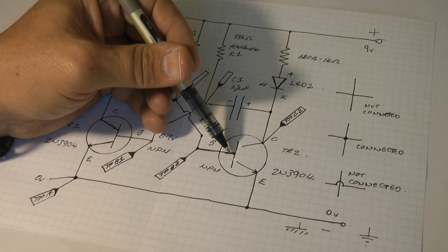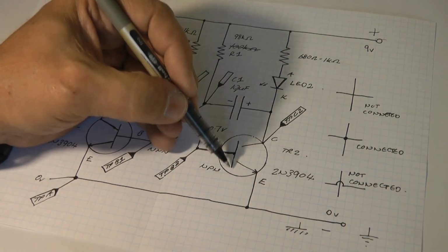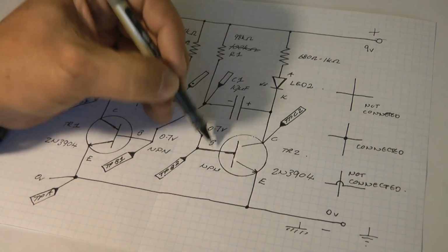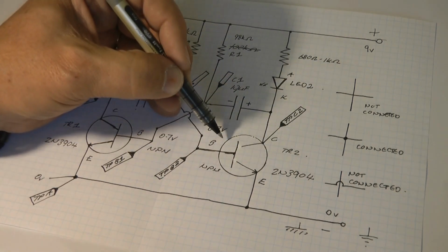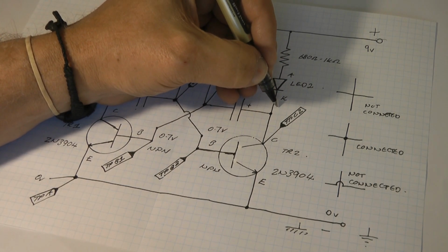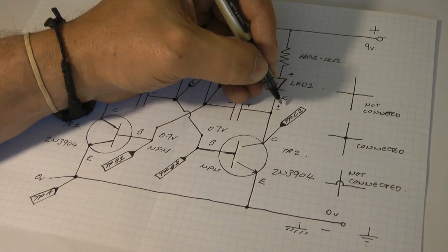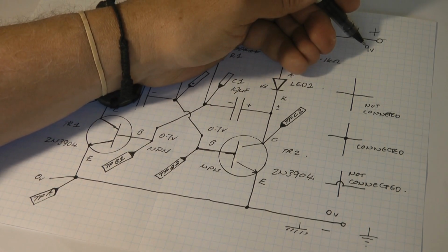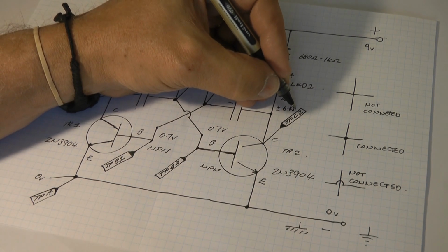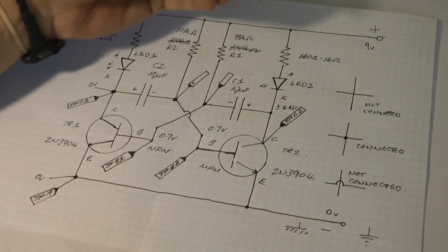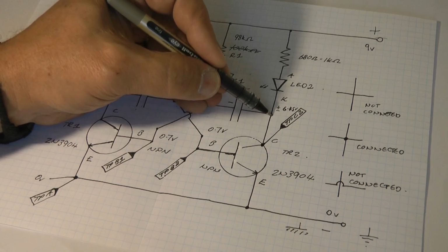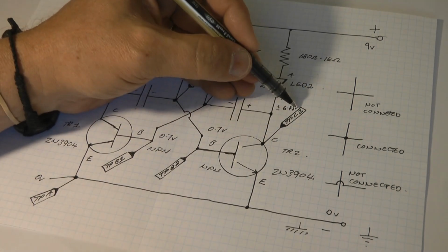But now what happens is, with this transistor in an open contact or off state, if we continue to compare this transistor to a physical switch, that means over here we might see plus or minus somewhere in the region, depending on the condition of our battery. We might see about, say, 6.45 volts over here at test point C2, because remember, test point C2 and this point, they're the same point, they're all connected.